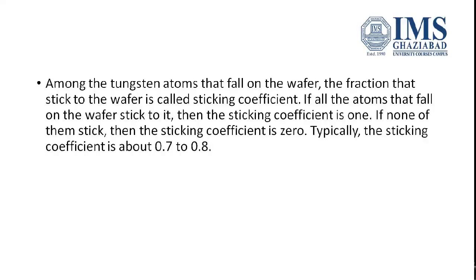Among the target atoms that fall on the wafer, the fraction that stick to the wafer is known as the sticking coefficient. If all the atoms stick, then the sticking coefficient is 1. If none of them stick, the sticking coefficient is 0. And usually it is 0.7 to 0.8.